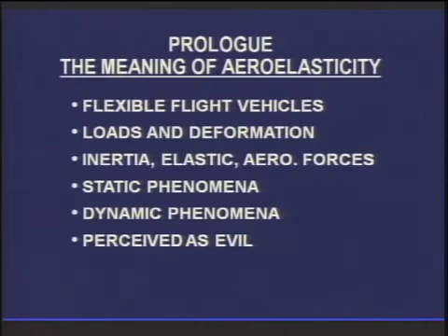There are three types of forces that are involved in aeroelastic phenomena. They're the structural inertia, elastic, and aerodynamic forces. Strength doesn't have anything to do with any of this stuff we're talking about. It's stiffness. How these three forces combine together determines whether it's going to be a static phenomenon or a dynamic phenomenon. If the elastic forces and the aero forces combine, then it'll be a static phenomenon.